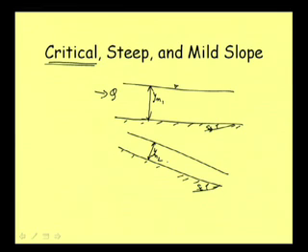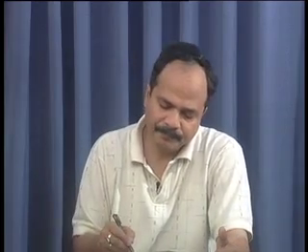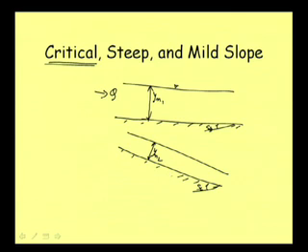Now, we know that for different slopes we can get different depths of flow as normal depth, given the other section and discharge are the same. Now, suppose for a particular slope we are getting a normal depth y n, and this particular depth itself is nothing but the critical depth, because already we know that for a particular discharge we can have a critical depth y c.